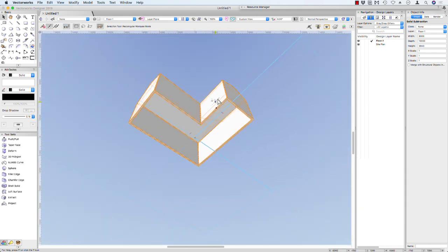So what I'd like to do now is to extrude an edge around my building. So I'm going to use my polygon tool to trace that over, or I could use something like a couple of rectangles and join them together. But I'm going to use my polygon. So let's use a polygon tool. You notice I'm just highlighting the blue bottom of my building. So click there, there, there, and I'm just going around the edge of my building.